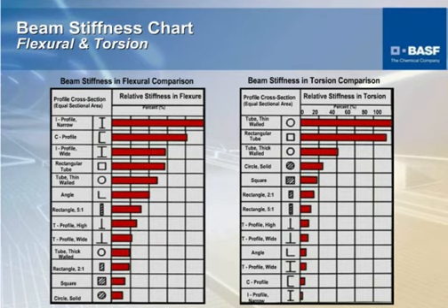And you can see in bending, the most efficient design is the I-beam, followed by the C-profile, and going down the line there are some tubes that are fairly efficient, and you can see that the solid sections are fairly inefficient in bending. At the same token, moving over to the right-hand graph, this one is for torsion. This is for when somebody is twisting something. You can see that the different cross-sections here are ranked differently from bending. The tube is the most efficient, the strongest in torsion, whereas the I-beam is actually the weakest, whereas the I-beam was the best in bending.